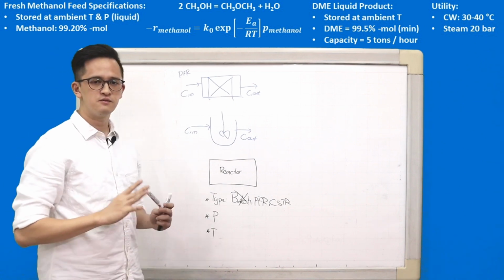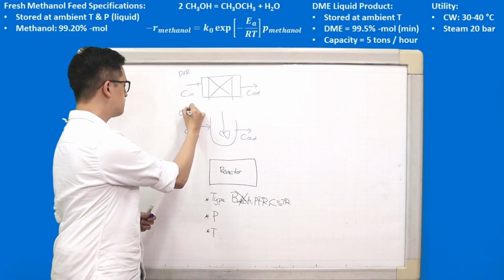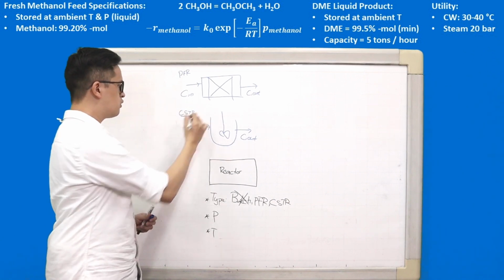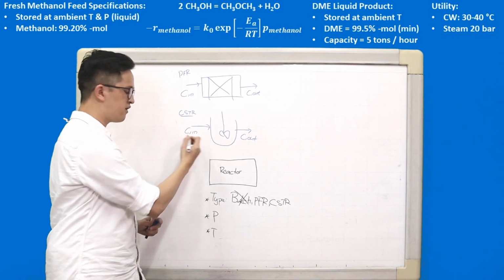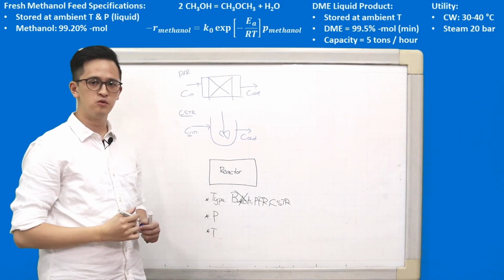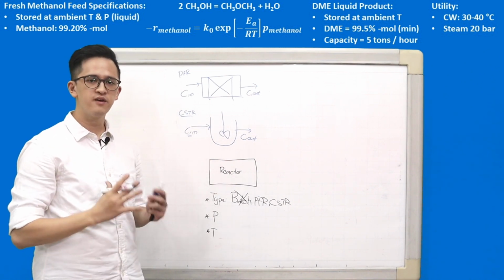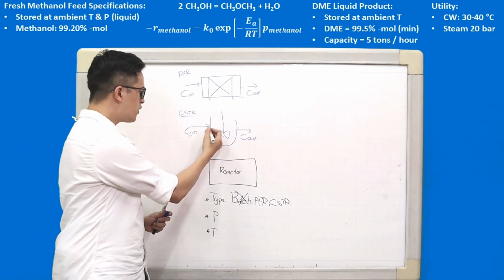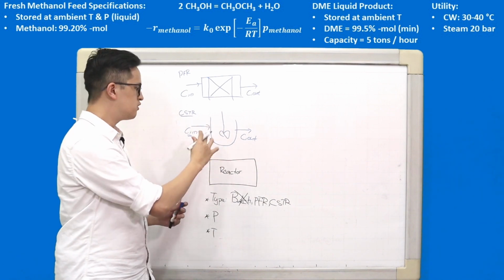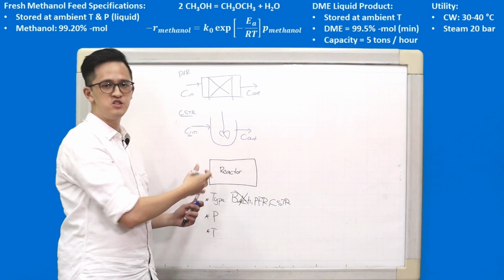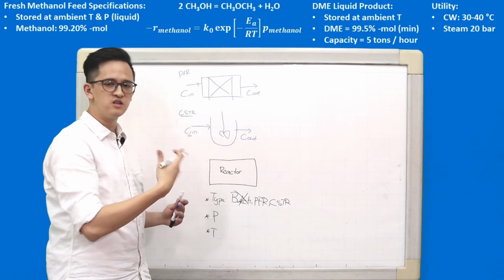And that's very different if we use the CSTR for the same reaction. What's going to happen is, when you put in the feed at high concentration, 99.2%, because of the characteristic of the CSTR, perfect mixing, that means once it enters, directly it will be mixed together into the equilibrium concentration inside of the reactor. So it's not going to decrease gradually.